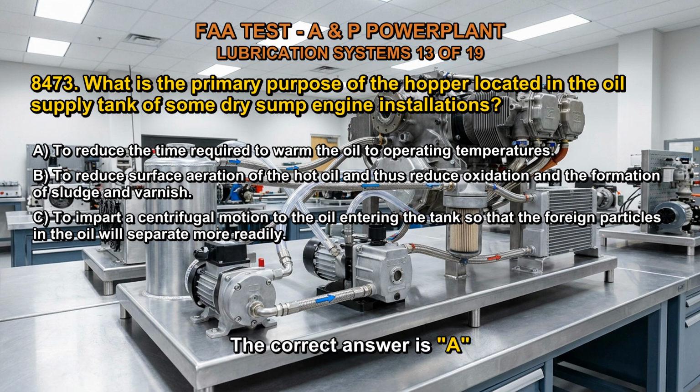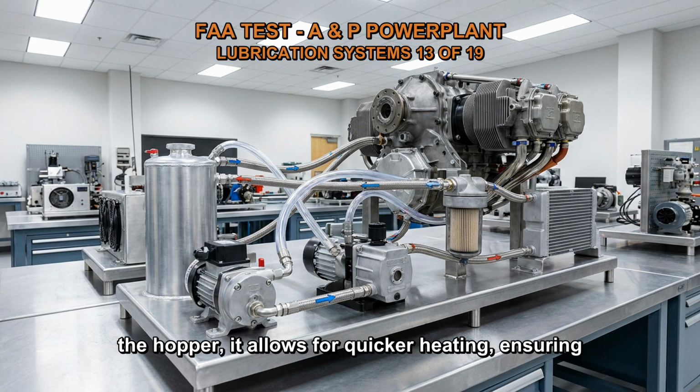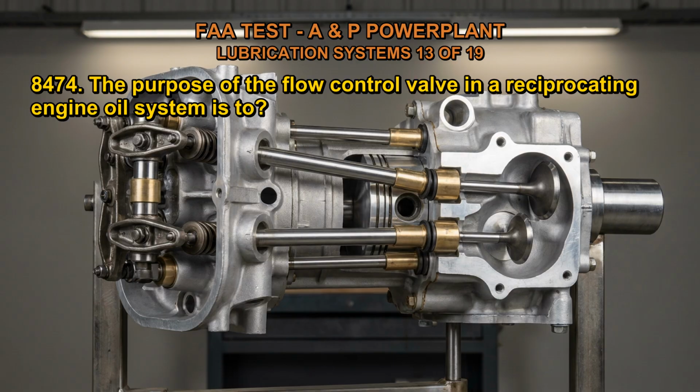The correct answer is A. The hopper located in the oil supply tank of some dry-sump engine installations serves to reduce the time required to warm the oil to operating temperatures. By providing a smaller volume of oil in the hopper, it allows for quicker heating, ensuring that the oil reaches the required operating temperature more rapidly.